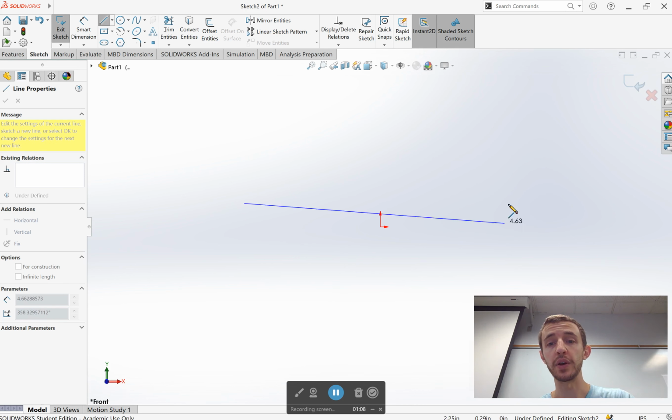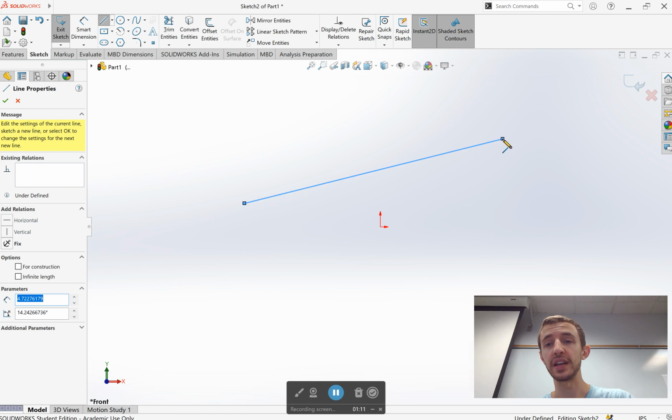Okay, so I can click anywhere I want, and when I do that second click, I actually begin a second line. When I begin the second line, you'll see several things. You see some yellow lines that are coming out of the original line. You see it right here, you see it right here, and you see how the original line turns orange whenever I hit one of those yellow lines. This is because SOLIDWORKS is saying, oh, is there a relation you want to add here?